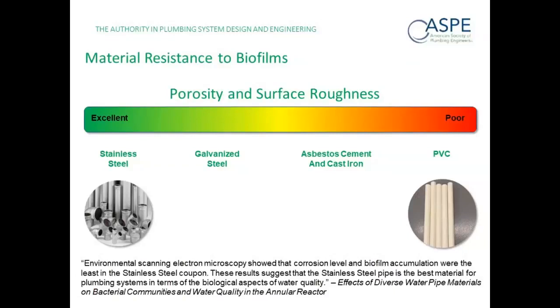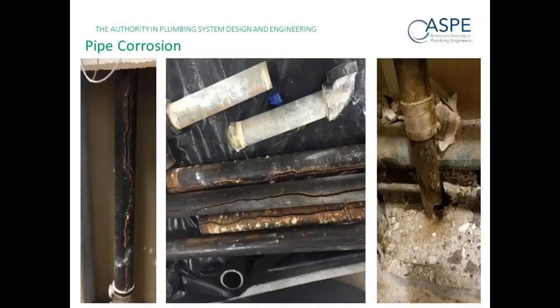And we're trying to use, especially in the food and beverage industry, and any critical care, or if it's life sciences where you have bacterial contamination, whether it be human or animal waste, stainless steel really is the way to go, just because of the porosity of it. And as Jimmy said, the advance of biofilm over time. It's really racing against the clock. If we can mitigate the risk associated with biofilm growth, as you mentioned, as much as 3, 4, 5 millimeters a day, you can grow biofilm. It doesn't take long for you to have a massive problem in a facility.